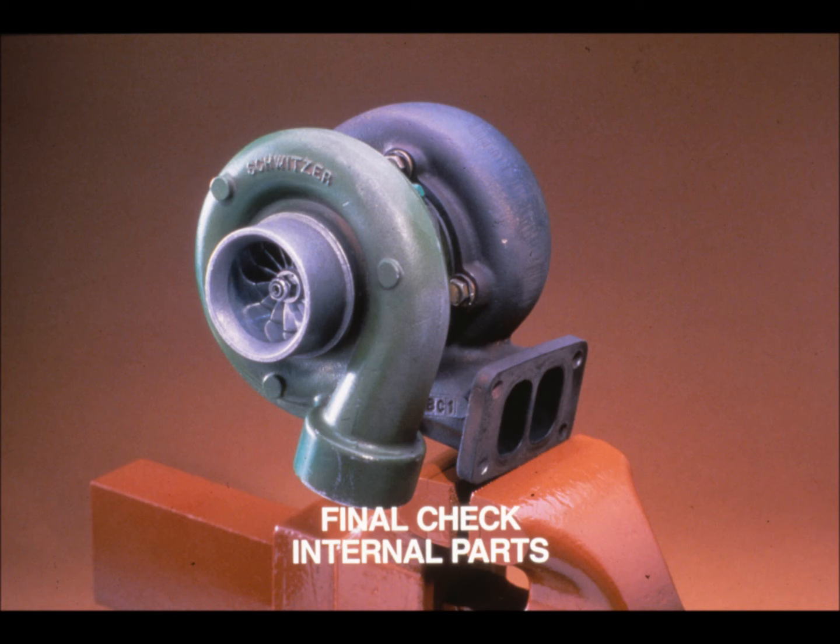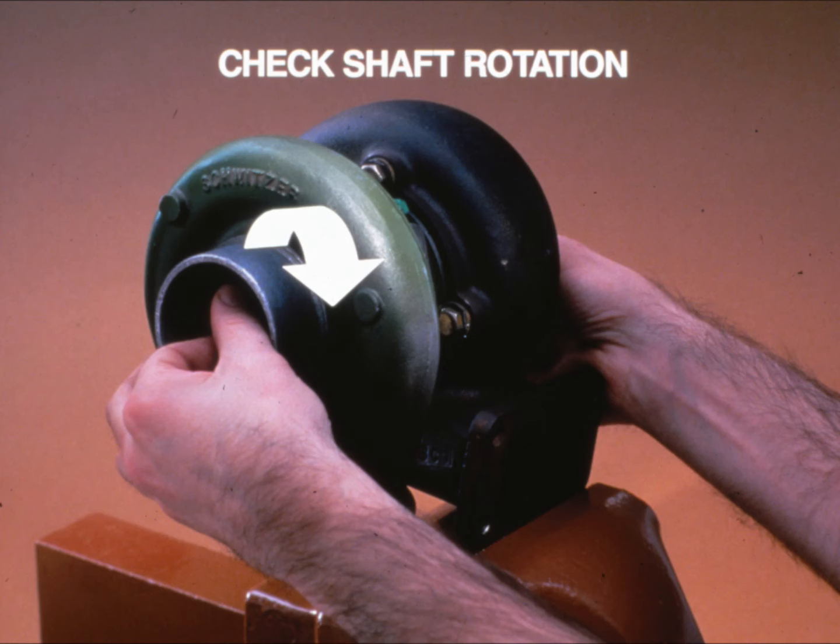The final step in the turbocharger inspection procedure will provide information about shaft rotation and clearance. Mount the turbocharger in a vise and check shaft rotation and clearance. First, rotate the shaft. It should turn freely. There may be some drag, but the shaft should not turn hard.